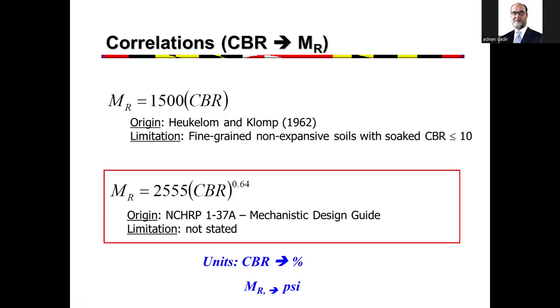It must be noted and remembered that even though CBR value is taken as a percentage, in all the calculations we perform we don't consider the percentage. For instance, if I say CBR 10, actually it is 0.10, but with the MR relation, we consider 10.